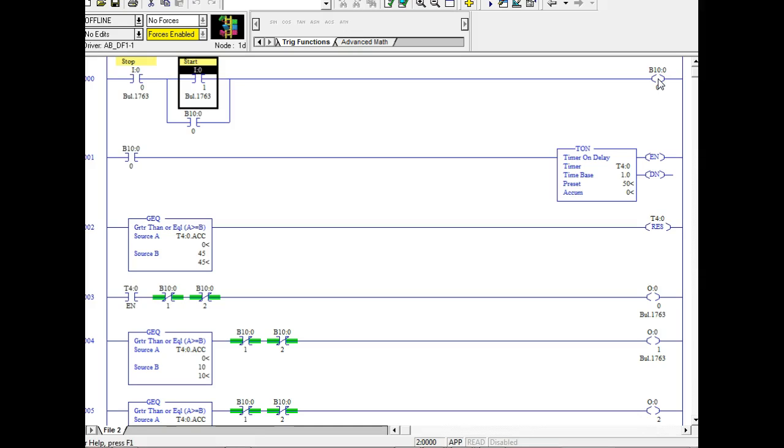So instead of burning up the motor, we have a detection out there that detects if the motor can't get started, or we make it try to develop too much horsepower, then it kicks the overloads. So if you got a contactor that's got overloads on it, then that's what we call the motor starter. And that's the only three that we got. Now, PLCs, we've only got two. We have what we call internal relays.